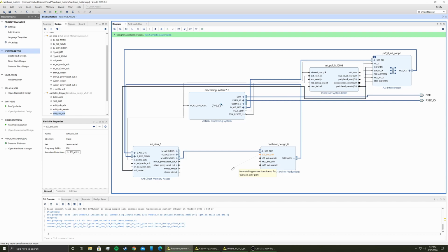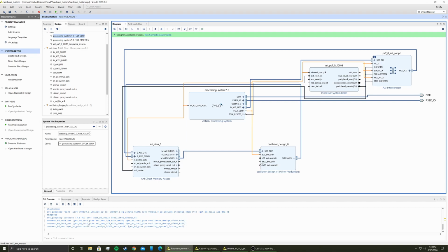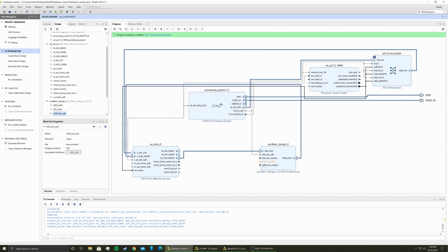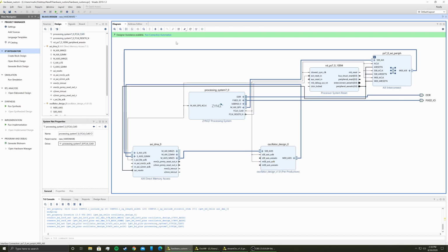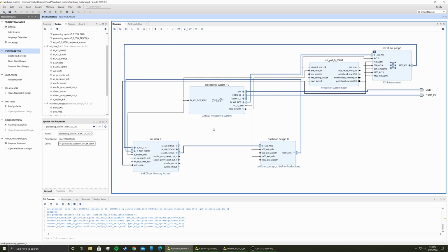We'll just leave this as the system clock. If you have a different clock, you can use that one as well. But we'll be just connecting these under the general system clock. So let's see if I can connect this up to here. Unfortunately, it does not like me at the moment. I'm selecting the incorrect one. That's why. It's not letting me select the correct wire. But yes, we'll connect this to the clock up here. Let's see. Yep. Connection automation just wanted to connect that.